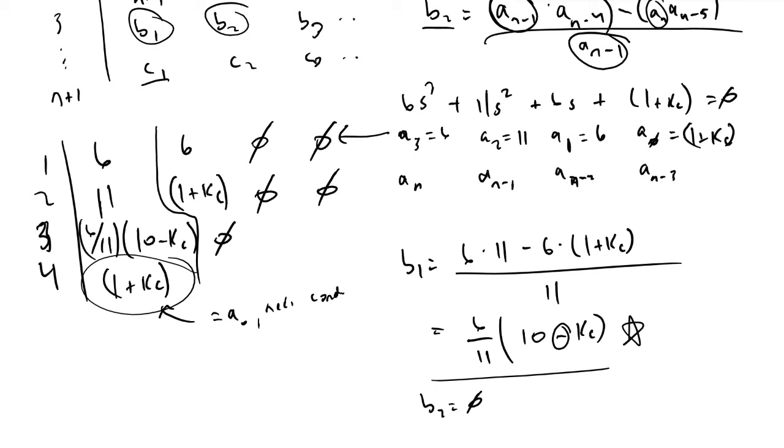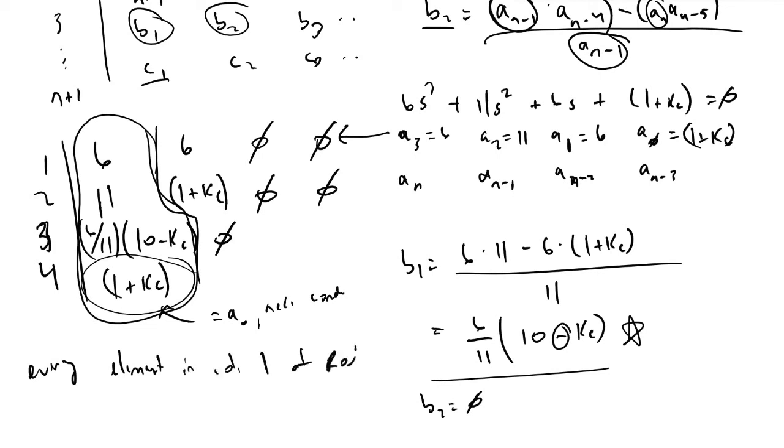And so the gist, or the holy grail here, is this column 1 of our Routh array. And so what our Routh array is telling us is that every single element in the first column must be positive.